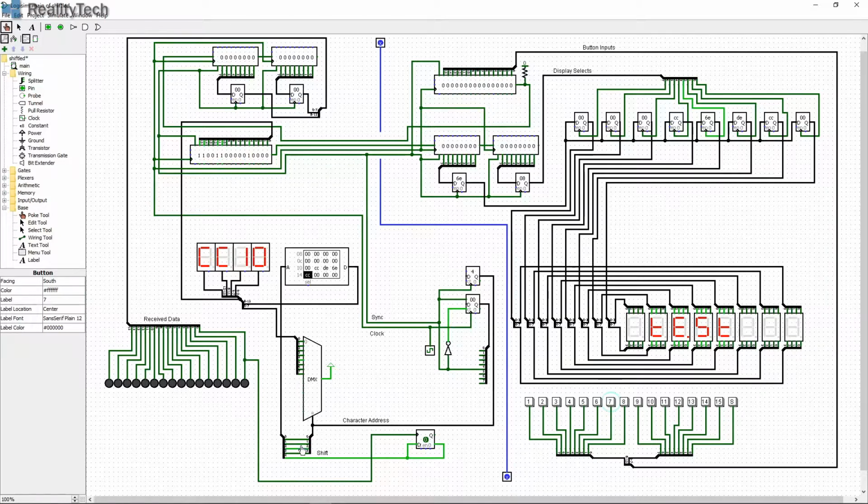So these 4 bits are used with this shift input to select an address in the EEPROM, and as you can see, what we're doing is adding the value of this bit to the output of the counter. And if I press that shift to turn it off, you can see we're looking from 00 to 08, which gives us our 8 characters, and you can see there is data in here. When we shift, you see that it asserts that adds 10. Sorry, that adds 16 to the address, and you can see we're now looking down here at these.